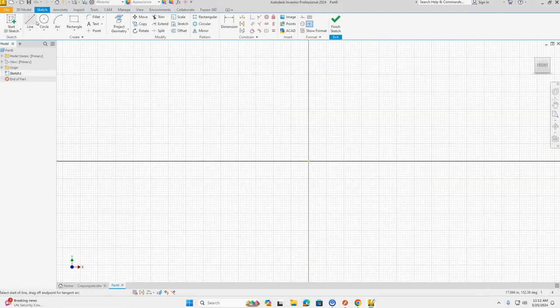We're going to use our line tool from the ribbon bar at the top. We're going to go to our origin. Once we get our green dot, click, let go of the mouse button, stretch out this line. We want to make sure that we're straight, and if you could see when I'm here and it snaps, you get that little gray box and you can see 0.0 degrees. We want to make sure we're at 0.0 degrees. Take your hand off your mouse and we're going to type on the keyboard 1.50. Once you've typed 1.50 and we're at 0 degrees, press enter on the keyboard.